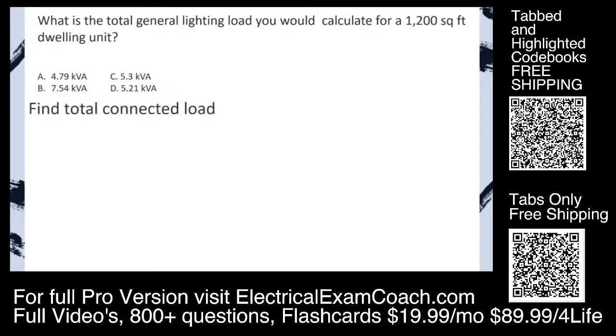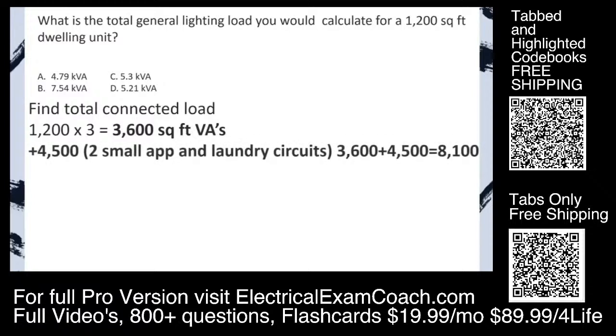Step 1, find the total connected load. We're going to take our 1,200 square feet multiplied by 3 VAs per square foot, and that's going to give us 3,600 square foot VAs. Now we have to tack on our 4,500 for our 2 small appliance and 1 laundry circuits. 3,600 plus 4,500 equals 8,100. Now we check for demand factors.